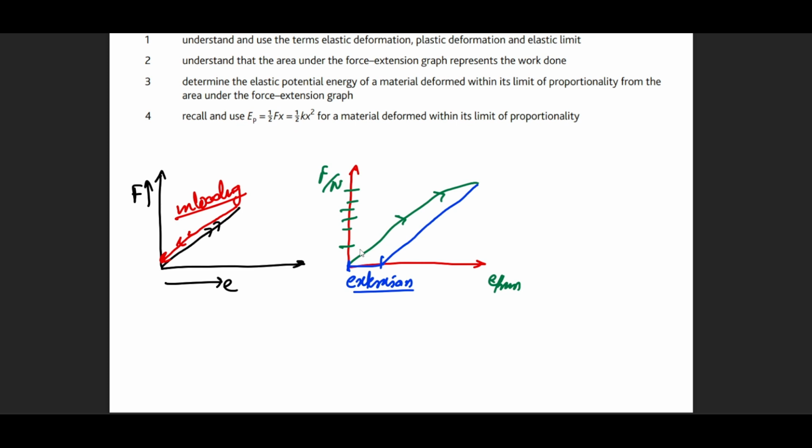And elastic limit actually goes back to the concept of limit of proportionality as well. So what is this point? This is actually a physical point. So first we encounter the limit of proportionality as L. This is a mathematics problem. Then just beyond this point, we encounter a slight change of path, which is a bit more curved than the rest of the graph. There lies a point of elastic limit. Now, this part does not follow Hooke's law, but it still mechanically tries to regain its shape. If you start unloading the spring, it will still come back to the original shape. So this is actually known as the elastic limit.